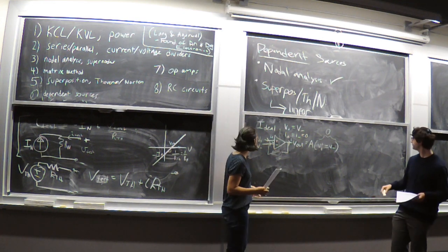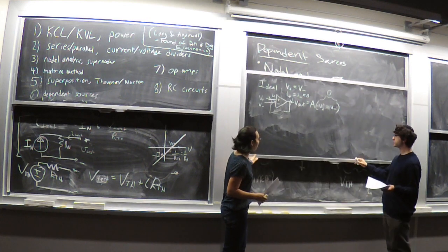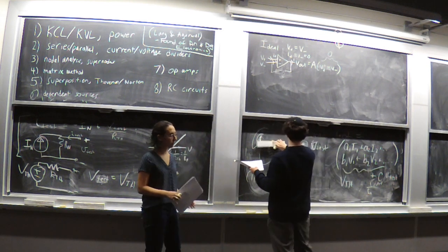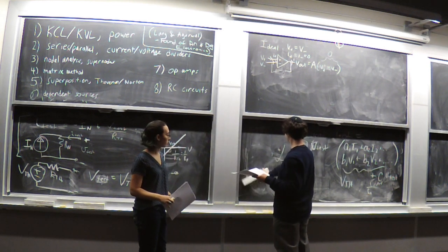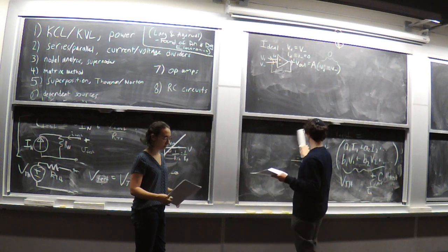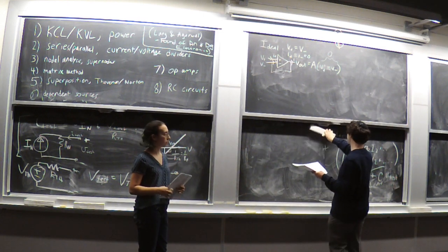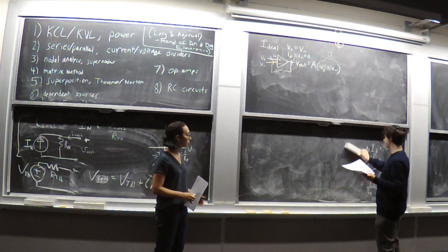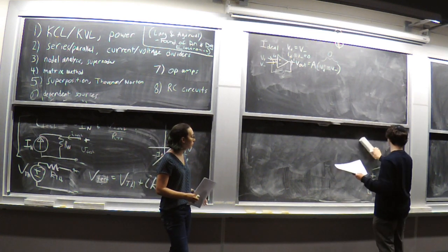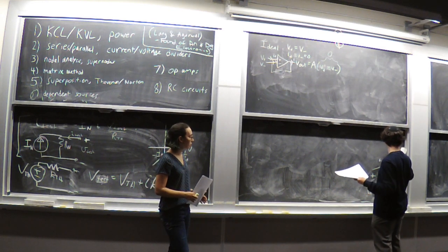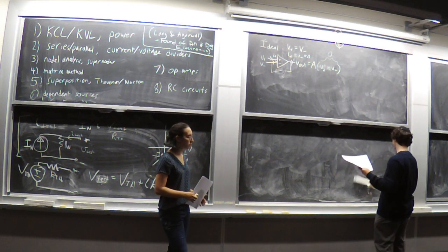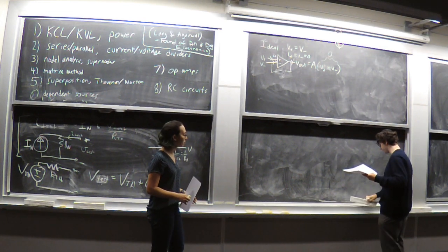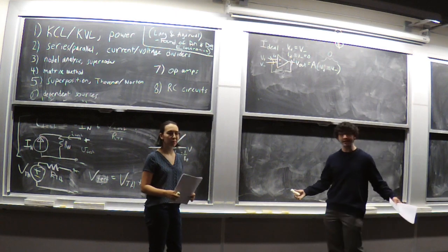Okay. All right. So one common thing to do with an op-amp is to make some sort of amplifier. And so the idea is if we have some input voltage and we want to scale it by some fixed amount to get our output voltage, we can set resistors up alongside the op-amp and it'll do the work for us. Op-amps can also do a lot of other cool things. They can add, subtract, they can differentiate and integrate, believe it or not. It's very cool stuff. We will get to that soon in the class.